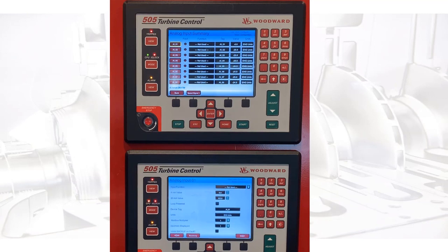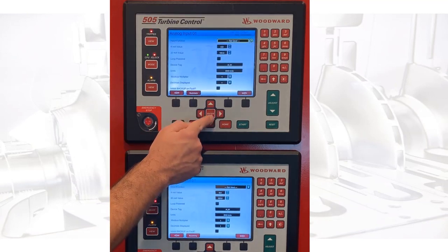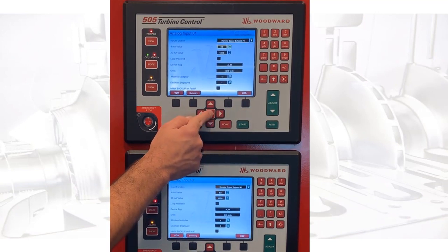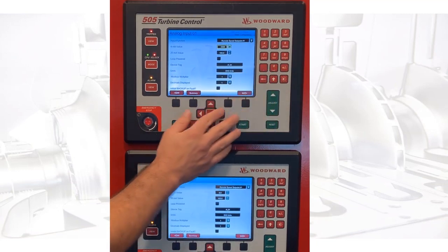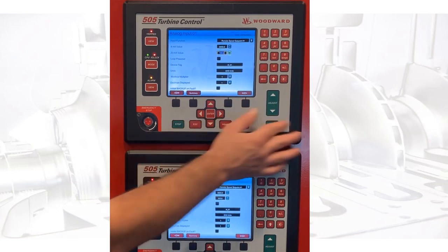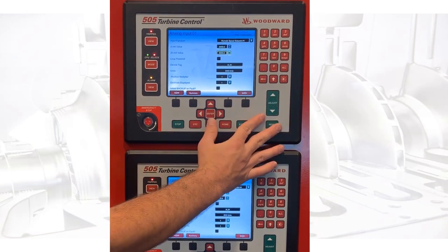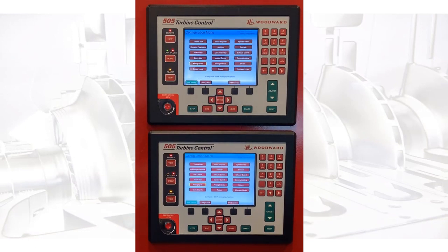This is because I/O is shared between the syscon and the backup. The analog input for remote speed set point comes into the FTM and then is shared between both units such that they see the same signal simultaneously. In this way, the analog input is configured identically on both units. The configuration is now complete, and we can exit configuration mode in order to show operation.